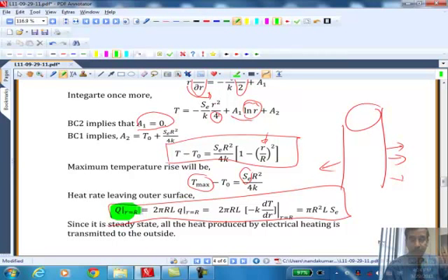That's what it in fact says, S_E multiplied by pi R squared L. Pi R squared L is the total volume of your cylindrical pipe. So that is the total amount that is produced, and that must be dissipated. But what we are saying here is I can calculate that amount by knowing the temperature gradient at the wall, because the Q that comes out of here is going to be equal to minus K dT/dr evaluated at R. That is, on the cylindrical surface, I am asking how much heat is leaving that surface.